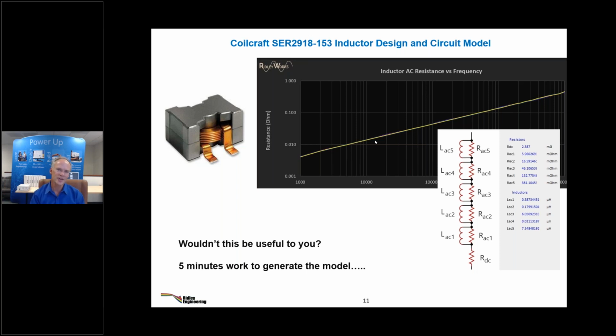Okay, but yeah, LTspice is really your friend on doing this, and I'm amazed how fast it can go on such high order circuits. And when we put core loss in, we put in another 14 L's into the model to do core loss as well. Maybe we'll repeat this webinar with core loss too, even though that one's a little bit more hairy to get your mind around.